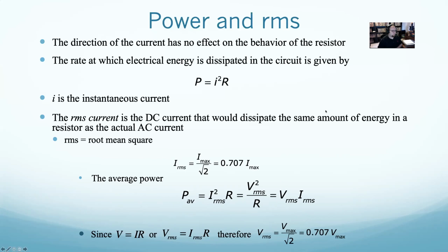When you mean dissipate, do you mean like that's the power loss over its travel time? That's the power loss of a resistor, because we talked about it before that any resistor has a power loss. P equals IV, or P equals I squared R, or P equals V squared over R, any of those equations. That's just the amount of power that a resistor uses. Normally it's translating into heat or something else, but that is the rate of power on a resistor. It's just what it dissipates. Now we're just saying on average how much it dissipates.